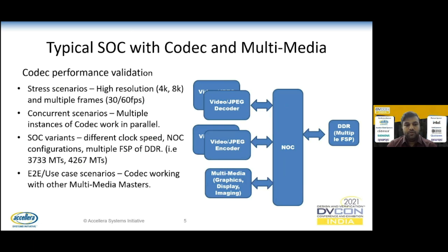Now coming back to a typical SoC with the codec and a lot of other multimedia blocks, here we can see multiple instances being defined. In our performance validation, we have to define stress scenarios, as I mentioned, with different resolutions, for example 4K and 8K, with multiple frames. We also have concurrent scenarios, where multiple instances of the codec work in parallel.